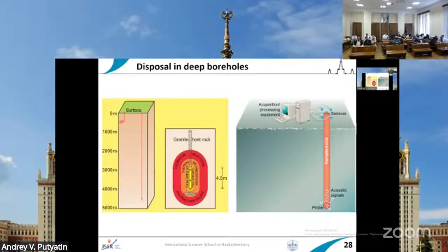Another type of disposal of high-level waste that is now under assessment and investigation is the very deep borehole. It is a typical deep geological disposal for high-level waste or spent nuclear fuel, a deep borehole or deep well down to 4 or 5 kilometers. The idea is that you don't need to excavate all the granite rocks, for example, from these depths.